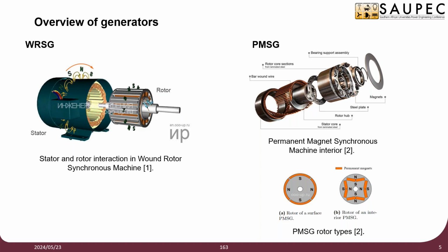The rotor options for its design are surface or interior permanent magnets. For this study, we opted for surface permanent magnets. These were chosen for efficiency, as fewer magnets are required, but unfortunately, this comes with speed limitations due to weaker mechanical strength than the interior permanent magnets.